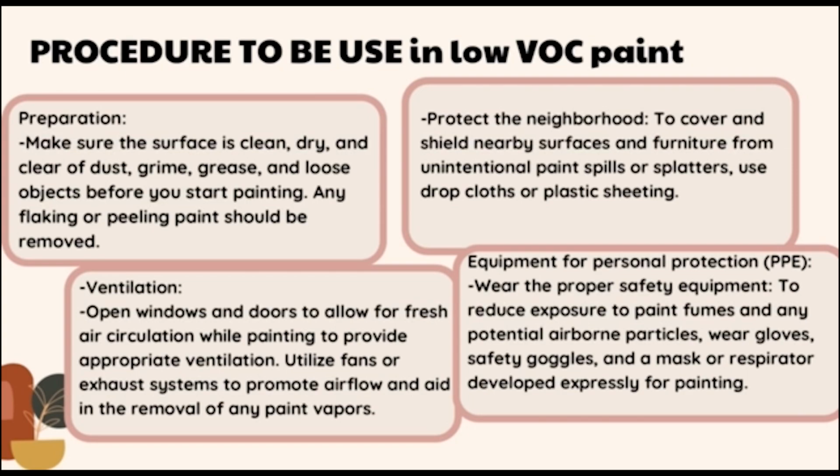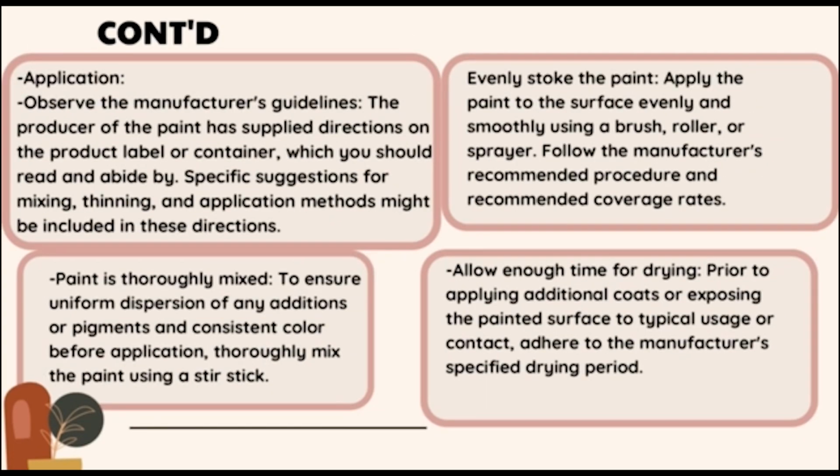So next, we should also use equipment for personal protection, which is PPE. We have to wear the proper safety equipment to reduce exposure to paint fumes and any potential airborne particles, and wear gloves, safety goggles, and a mask or respirator developed expressly for painting. So next, let's continue to the application.